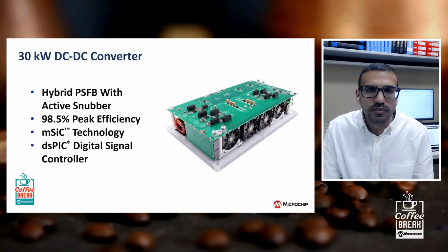Okay, my follow-up here would be, why is there such a wide output voltage from this stage? Yeah, typically there are 400 volt systems. Electric vehicles will have 400 volts, but when we say 400 volts, it doesn't mean exactly 400 volts. There's different ranges for each vehicle. So you may have a max voltage of 420 and a minimum of 300, or the minimum might be a little lower, maybe around 200 or 250.